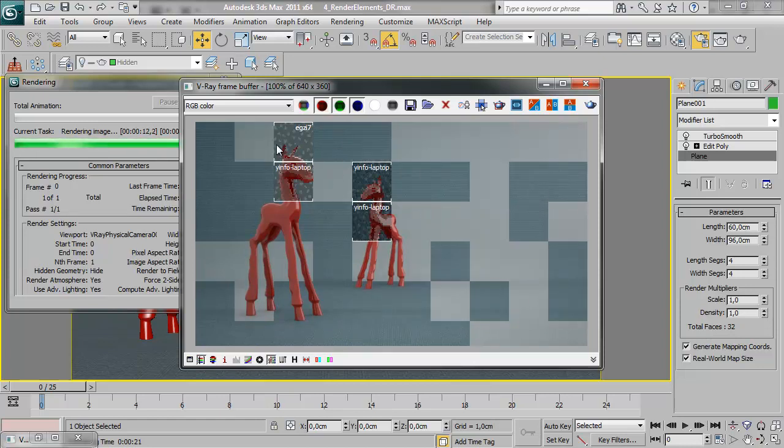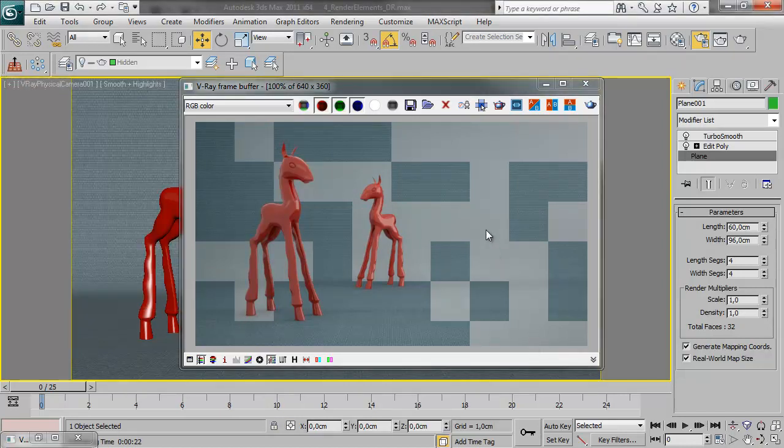And as you can probably tell, I'm only rendering on 2 computers right now, so troubleshooting wouldn't really be that time consuming. But if you're on a big render farm with a long list of DR servers, then finding out which computer is not picking up textures or irradiance maps or light cache files could take a lot of time.